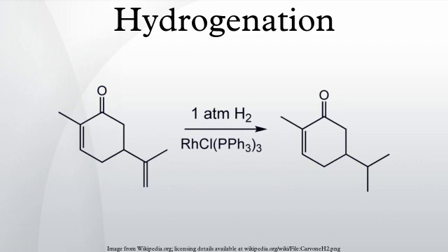Industrial applications. Catalytic hydrogenation has diverse industrial uses. Most frequently, industrial hydrogenation relies on heterogeneous catalysts. In petrochemical processes, hydrogenation is used to convert alkenes and aromatics into saturated alkanes and cycloalkanes, which are less toxic and less reactive. For example, mineral turpentine is usually hydrogenated. Hydrocracking of heavy residues into diesel is another application.